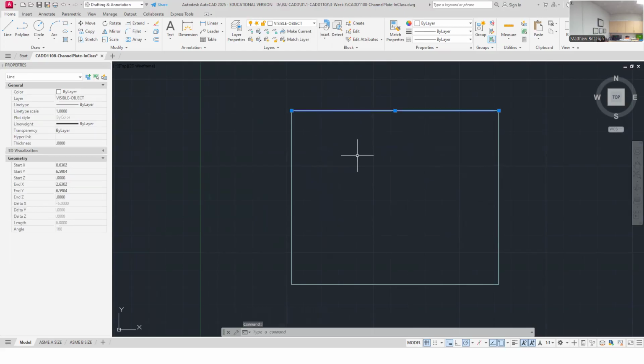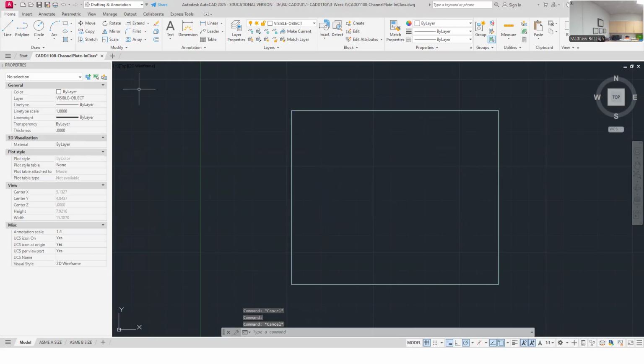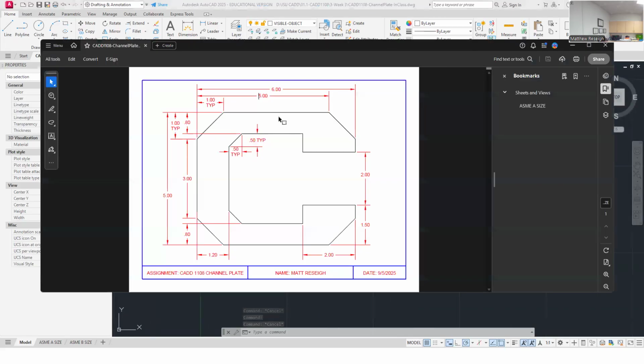The individual line segments. One thing I might do, just as I see to draw this, is choose the offset command to offset these lines in here to get this line segment here, and maybe I could offset this one. They're different offset dimensions, but let's just figure it out. If I offset to create this inner line, I'm going to get some overlapping lines. That's okay. I can trim them. So this offset is 0.8 top and bottom, and then right here it's 1.2 offset. So I've got two different offsets. So let's go do this. I'll offset those first and then trim them up a bit.